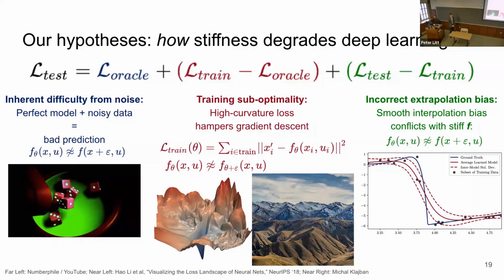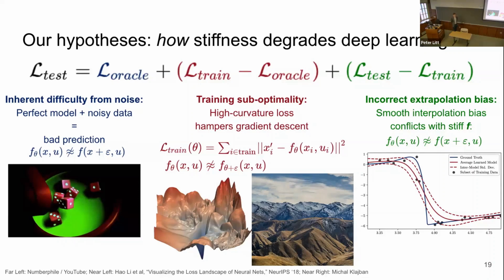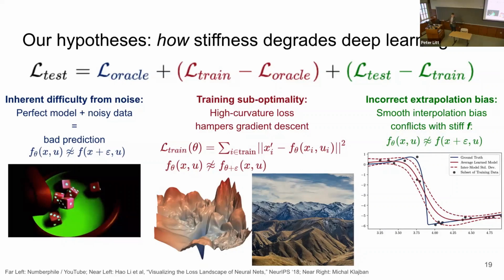But from my understanding of the analysis, it actually really doesn't matter, right? You could very well incorporate errors in actuation. But in a very pragmatic way, errors in actuation would correspond to errors between what actually is executed and what you sense, either through proprioception or through an effort command. Right. Yeah, I would say another thing is depending on the data you have available, this could be something you decouple, right? If you're modeling the inputs, the actuator outputs, and you're sensing them through, for instance, series elastic actuators, you could have that be the input in the model and completely worry about the actuator dynamics as a separate learning instance. Yeah. Okay.